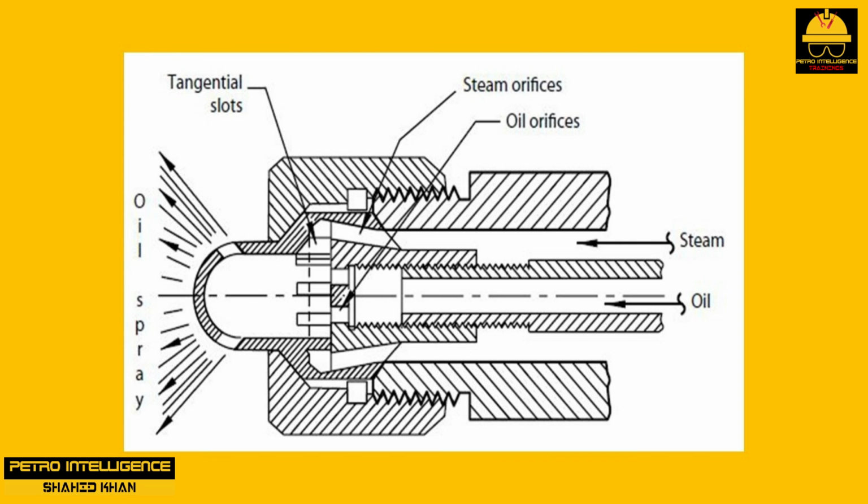The fuel oil flows from a circulating hot oil system kept at several hundred degrees F, depending on what is being burned. In most refineries, visbreaker or vacuum tower bottoms provide the fuel oil, which is circulated at about 500 degrees Fahrenheit. Burner tip plugging of the oil orifices shown in the picture is a routine problem. The most serious problem is loss of fuel oil circulation in case of an electrical power failure. The fuel oil can then solidify in the circulating system and in the burners themselves. For example, vacuum tower visbreaker bottoms can solidify at 300 degrees Fahrenheit.